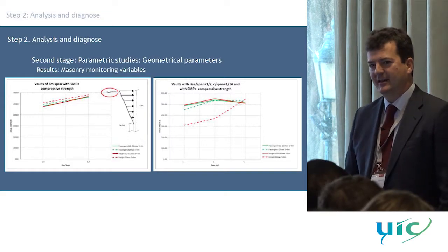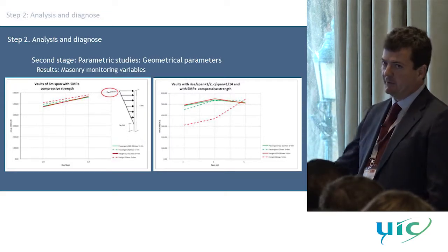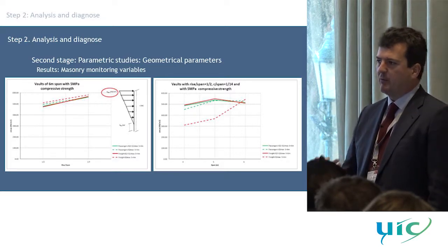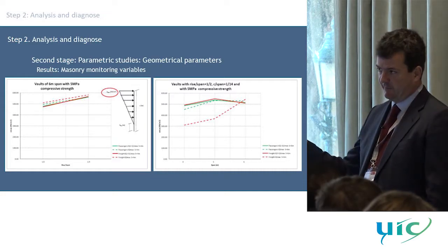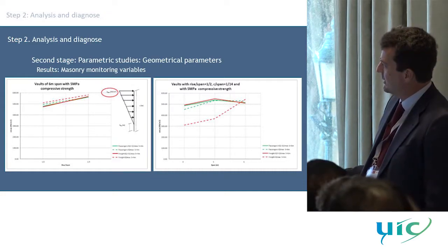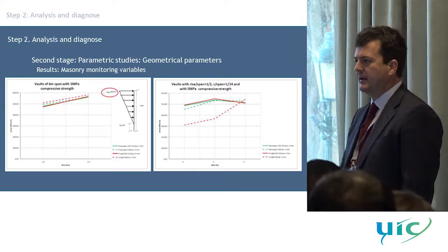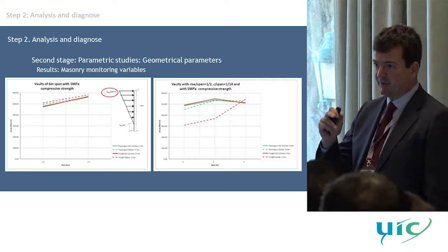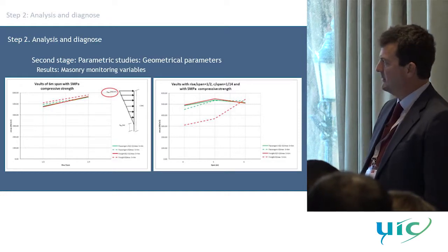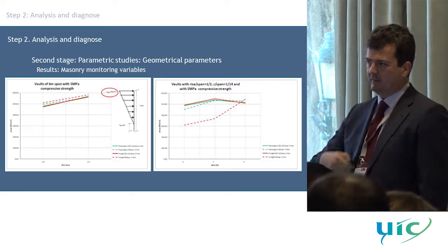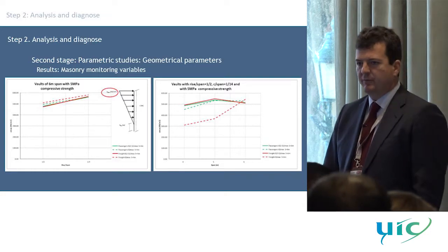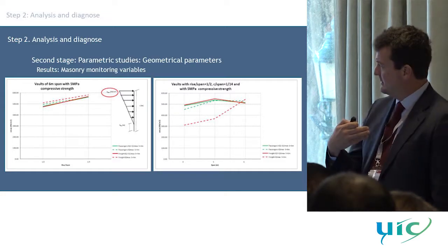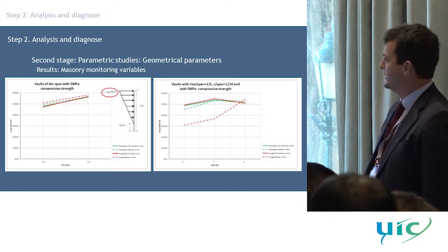There is no way that with normal analysis, with these properties, with real trains and with real geometries, we could have problems with stresses in a masonry arch bridge if this model is all right, because normally we are about 0.6 megapascal, 0.8, 1 megapascal, which is not a lot for peak stresses, not for mean average stresses in the section. So it's quite difficult, if all of the elements are healthy, I mean, the infill is well compacted and the masonry is all right, to blame the stresses or strength problems in the masonry arch.